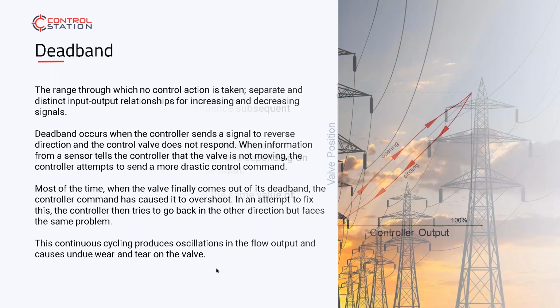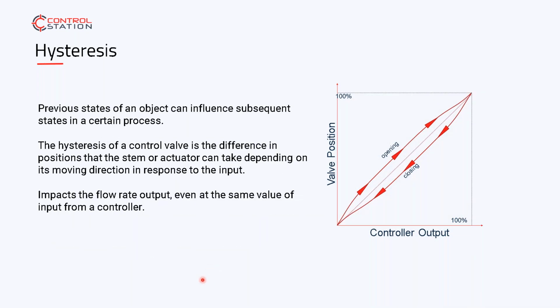Moving on from deadband, we're going to look at hysteresis. Now, hysteresis is more like a process-related problem, but can be mechanical too, in that the action of the process exhibiting in our system will exhibit a different profile in the upstroke than in the downstroke.